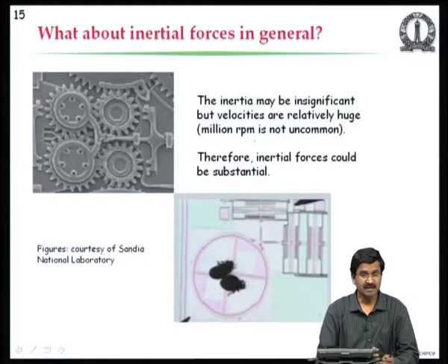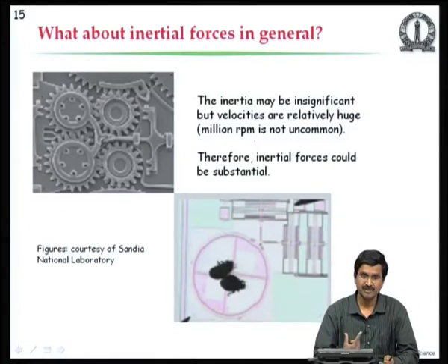If you say that the self weight, which is an inertia force, is negligible, we do not need to worry about it at micro scale, but what about other inertia forces like centrifugal force? If something is spinning, there will be centrifugal force on it. In the context of gyroscopes, we had discussed that. Should we worry about these inertial forces that come because of rotation, structures that are rotating?